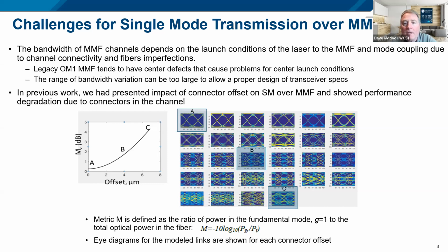What is the maximum achievable reach, Bulent? Yes. If you use two of these mode field adapters at the beginning and at the end, you could go to a couple of kilometers. And actually, one of the vendors of these mode field adapters reported to us that they had actual working lengths in the range of 6 kilometers for 10 gigabits. So they could go quite long distance.